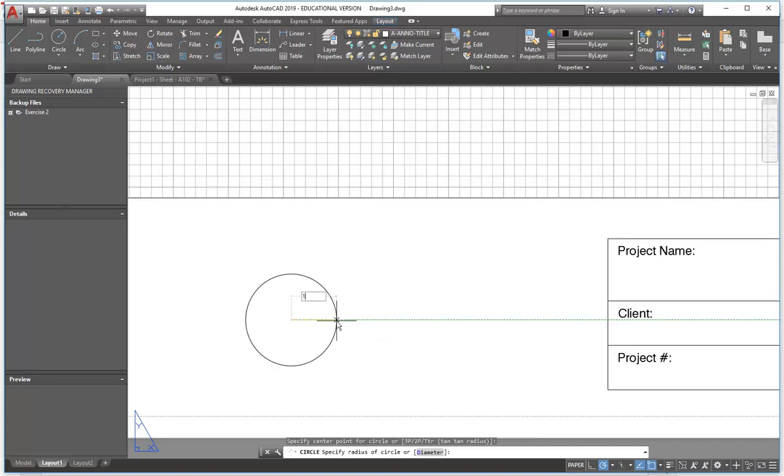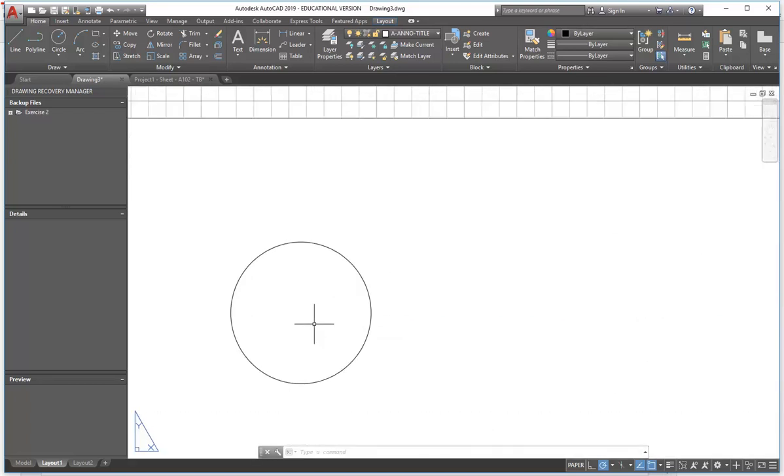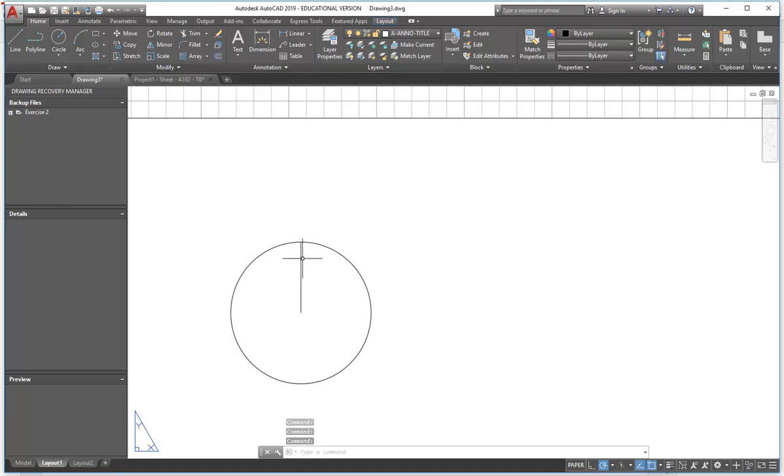That kind of works. Because notice we're not drawing in model space, so we don't need to scale it. We're drawing it in layout, so it's 1-to-1, the size it would print. And for north points, you're going to steal mine now, and I didn't design this, but I'd like to think I did. That's my north point, and I just give a heavier line weight to this line, and that does it for me. Yes, I know, there are lots that are basically the same, and I thought I'd come up with it.